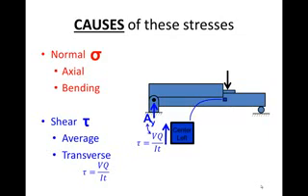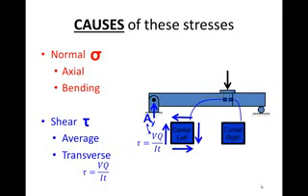And the V, or the shear force in that equation, would be equal to the reaction force there, or the force that's trying to cause it to shear. And because it's up on the left-hand face, there must also be a corresponding shear stress down on the right-hand face, as well as stresses in these directions on the top and bottom faces.